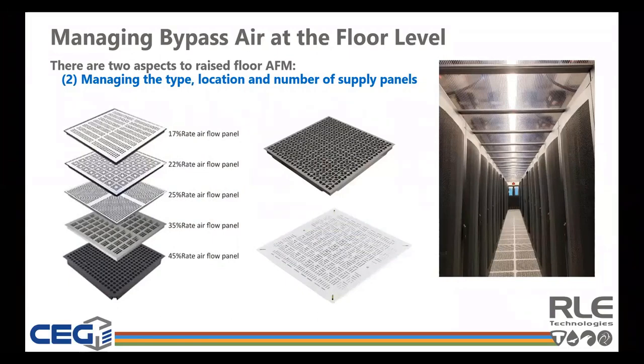We're going to talk now a little bit about airflow panels and managing bypass air. Airflow panels should be managed so that they're in the right places, providing the right amount of airflow. And we'll talk a little bit more about how to determine this in upcoming slides. Dampers should also be used on airflow panels planned for future growth or where IT loads are lower now but may change over time.